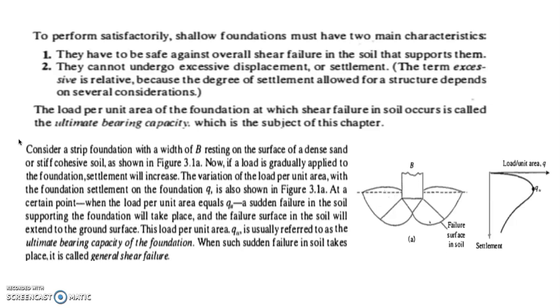When we talk about shear failure, of course, we know that shear failure is a failure that takes place due to insufficient shear resistance available between the materials. Shear failure can be determined by excessive deflection and development of cracks, which gives us advanced warning about the probable occurrence of shear failure.